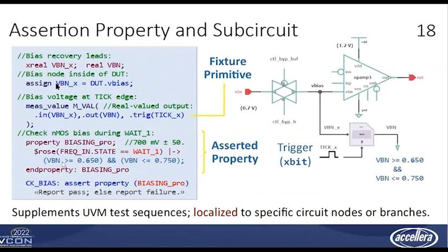And as long as the overall expression evaluates to Boolean, this is correct SVA syntax. And by the way, the clocking event is specified as a default within the fixture submodule.